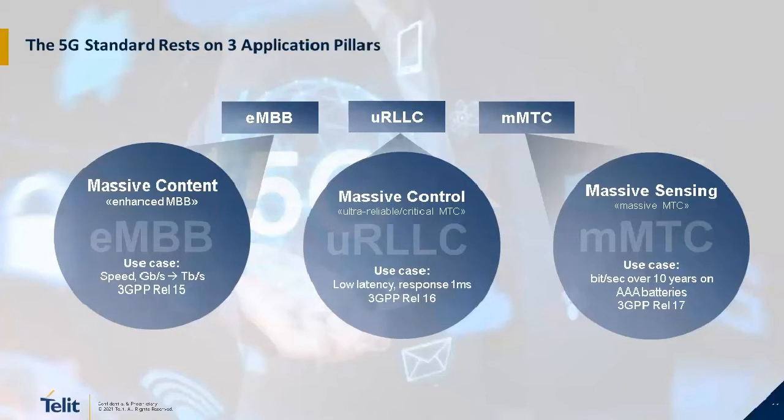So that's one. Then let's move over to the middle one, ultra-reliable, low-latency communications, which is the mouthful acronym, URLLC. This is something that 5G is promising with Release 16, where the latency, which is the end-to-end delay of the wireless network, is sub 1 millisecond. That's really fast, which means that a wireless network in, for example, a manufacturing environment can allow robots and machines that are building cars or doing whatever to talk to each other very fast over a wireless network.